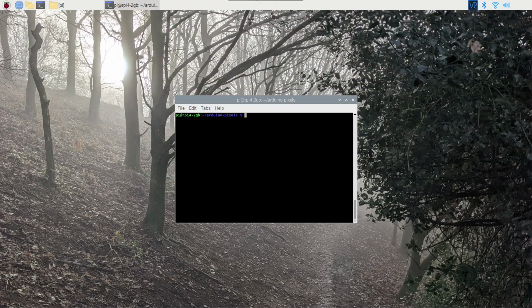We've shown 3 different tools here. One thing to be aware of is to be very careful when you're mixing and matching them. If you open up a terminal window using the command line, then you're not going to be able to use the terminal and transfer files in, say, using the OpenMV IDE or Thonny. While I was doing some testing on this, I couldn't figure out why OpenMV couldn't connect, and I realised I'd got minicom still running in a minimized window.